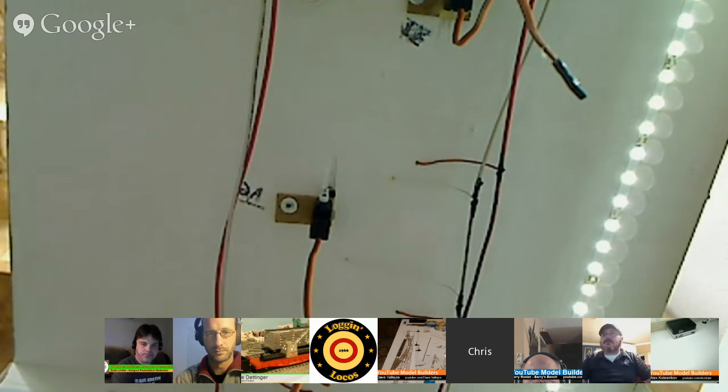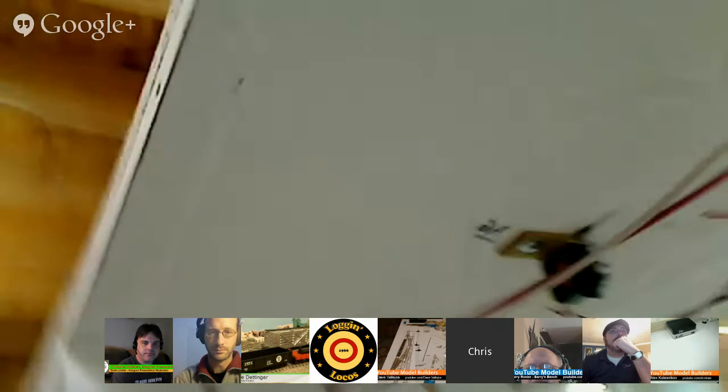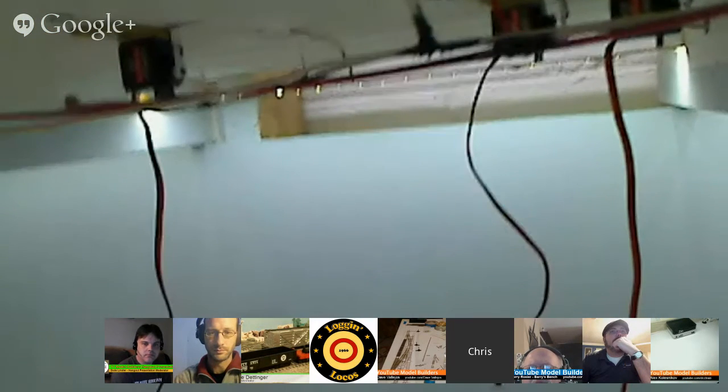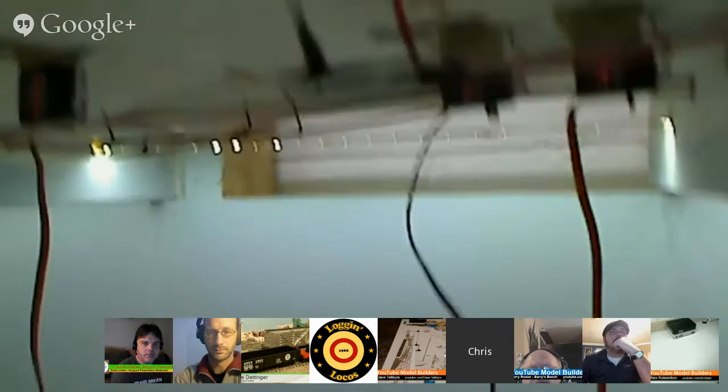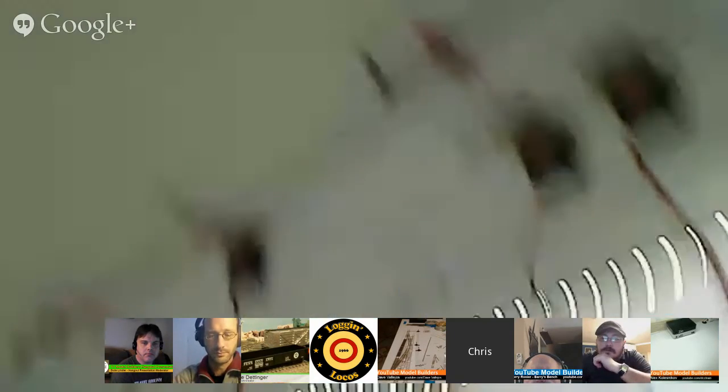They have a flexible tube and wire that you can use with bell crank linkages, and you could use that with these because it came from RC servo controls for aircraft. You mount your servos in the body, with the tube and push rod going out to a crank lever for an aileron on the wing. But yeah, you can do these fairly inexpensively.